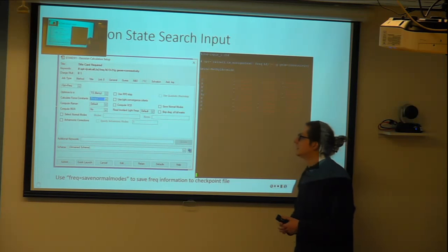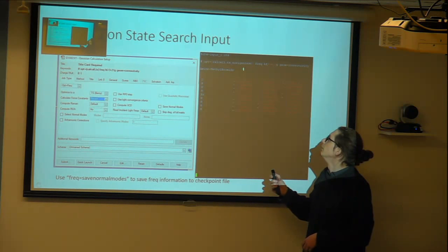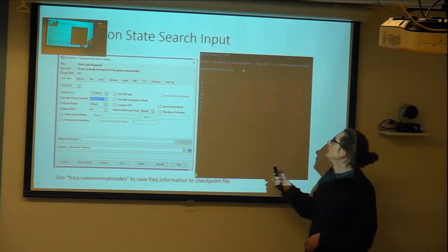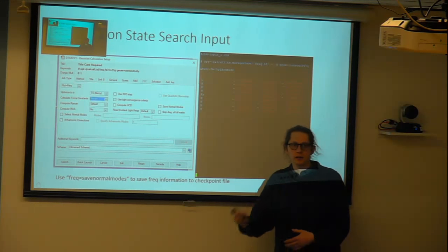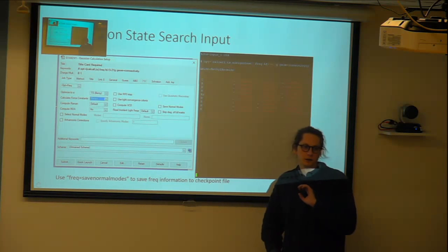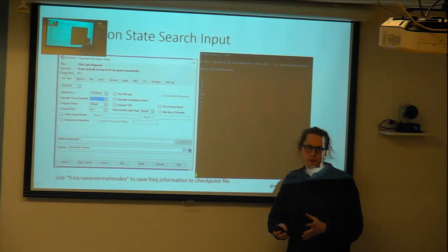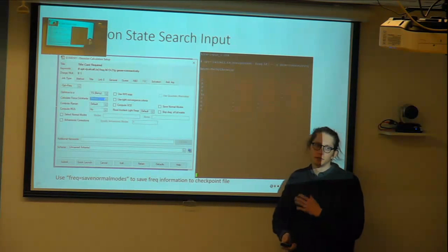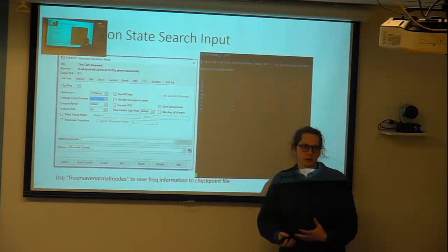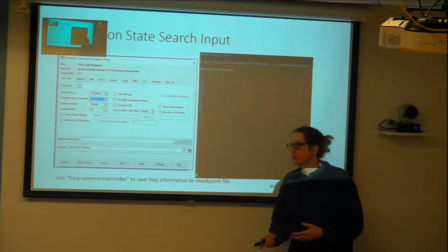And this is what the input looks like. You can see that I did one thing here that I did not put in GaussView, and that's I added noeigentest. This is because the first time I ran the calculation, it failed, telling me that it expected one imaginary frequency, and it got 4. I did noeigentest, which fixes this problem, but I've read that it can also lead to less accurate solutions.